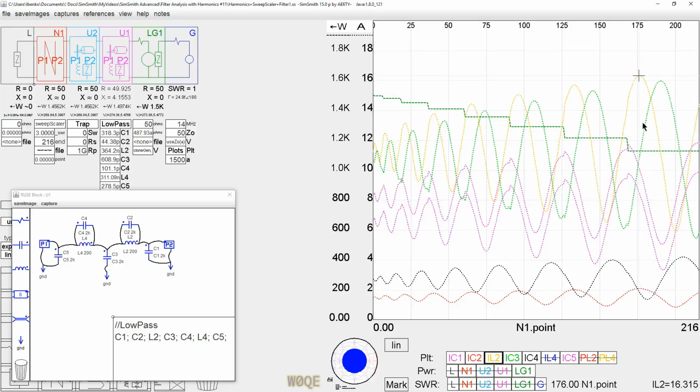And of course, instead of plotting this actual current out, I could have plotted just the peak, and that would have been fine too. But it's 16 amps. 16 amps in that inductor, it doesn't need 12 gauge wire. It needs a lot more than 12 gauge wire on 20 meters or it's going to get warm. Let's look at the power in that inductor.